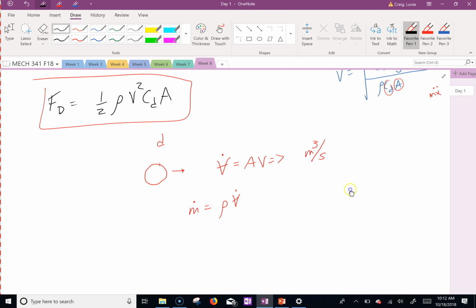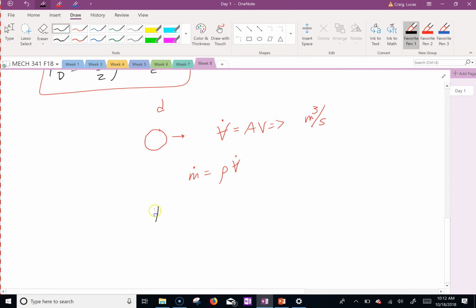Last chapter, we knew that if you had flow shooting at you or flow going out, what was the general equation of force for fluid? M dot times the right side of Newton's second law, which was the summation of m dot times v, in and then out.